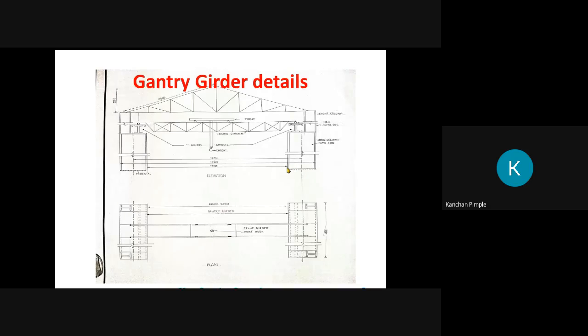Then as per your column design, if the size is ISMB 500, then you go for the same. If the size is different, you have to first design the column. Then only you have to draw this. Gantry girder, you have to design the gantry girder, and as per your gantry girder, maybe ISWB 600, maybe ISMB 550, likewise. So you have to show these dimensions. And in your case, if rise is 3 meter, you have to draw this line as 3000, and draw these two lines and join this point to this so that you get a sloping length. Are you getting?